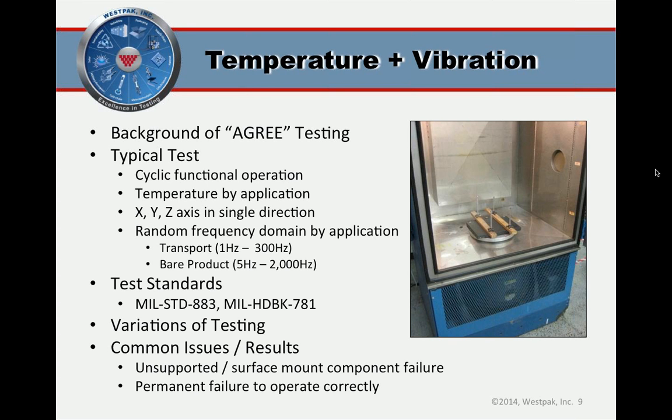So the test parameters themselves are going to be based upon your end-use environment. So if you had a product that could be subjected to something like this, you need to think about the environment. For our laptop, maybe it could be used in an aircraft or in an extreme off-road vehicle. Who knows? Something like that, where you get temperature and vibration extremes. So some commonalities, though, typically we'll have the unit turning on and off cyclically to stress its internal components and making sure it's still functional.